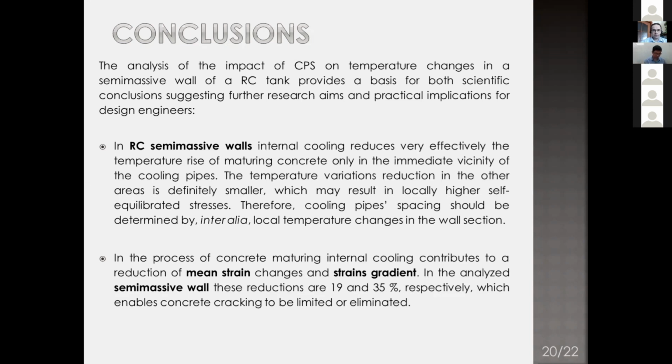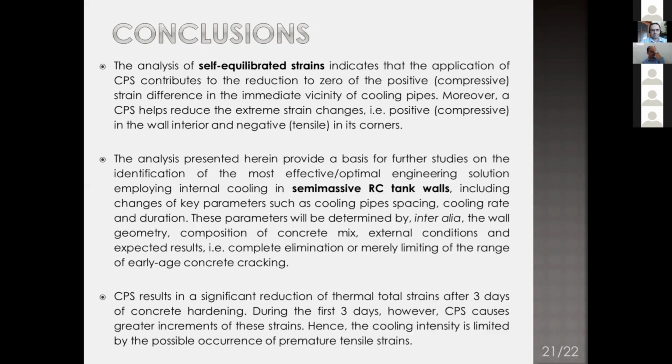The next one: in the process of concrete maturing, internal cooling contributes to a reduction of mean strain changes and strain gradient. In the analyzed semi-massive wall, the reductions are 18 and 35% respectively, which enables concrete cracking to be limited or eliminated. We have analyzed stresses in a previous paper, and we know that in the case of early age cracking, this solution eliminates the cracking. In the long term, some small cracks could appear.